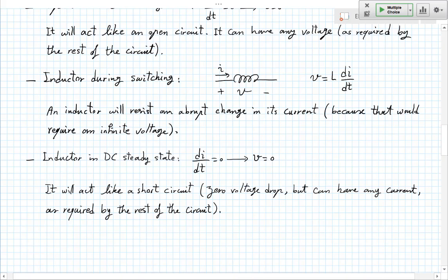The current going to it is 0. The tap is closed. And you abruptly open the tap. You change the current that goes to it. No problem with that at all, right? You change the current abruptly. What you can't change is how much water there is in it, because that takes accumulation over time, right? And similarly, then, the inductor does not care if you change the voltage across it abruptly. If you change V abruptly, all it means is that the time derivative of the current also changes abruptly. But that's quite OK.